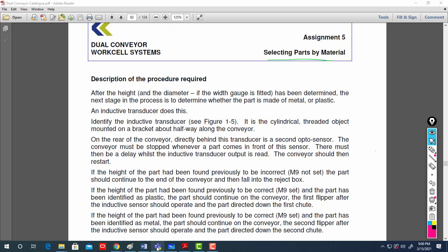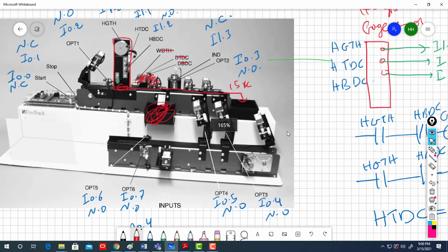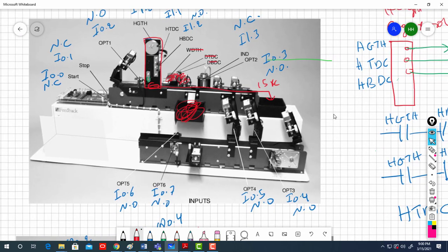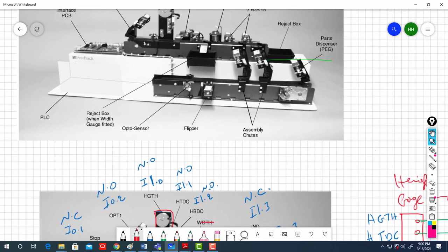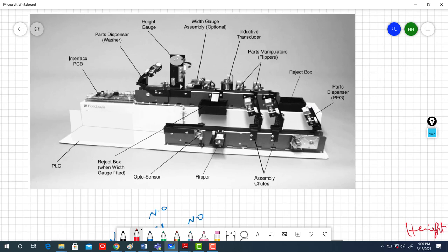And how to do that, in here, that's your conveyor, or if you want to look at it in here, after size is determined, you go here, and it's in this process you can decide if it is metal or plastic, because you have an inductive sensor which will be activated if it is metal, and if not, the part will be plastic.